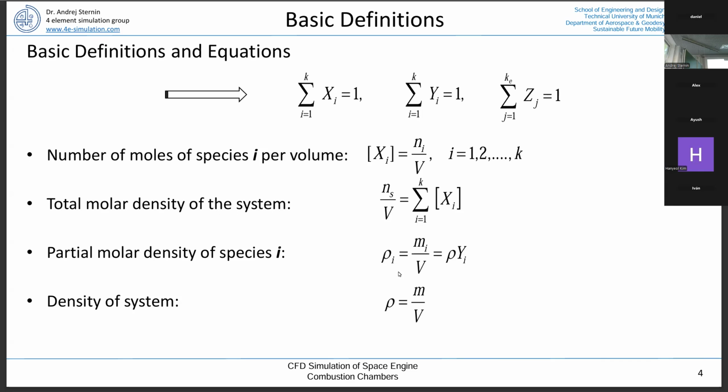This is important for those who know fluid mechanics. Typically we have the system of Reynolds averaging. If we have a turbulent flow, we have some fluctuations, and in principle Reynolds came up with the idea that any fluctuating velocity component can be subdivided into an average plus the fluctuation, the instantaneous velocity being an average plus the fluctuation. Now, this holds if you don't have large density fluctuations.